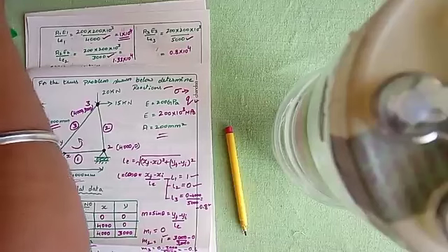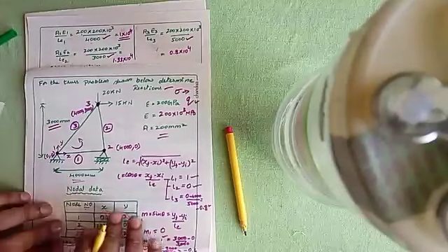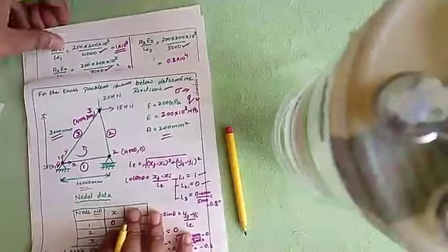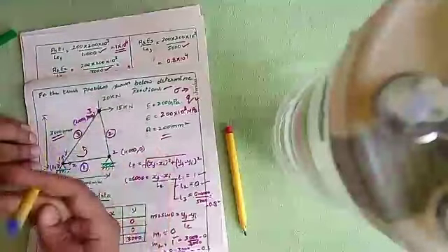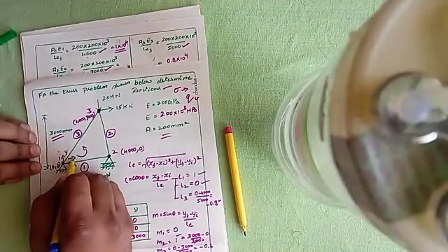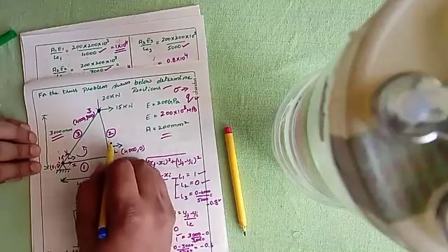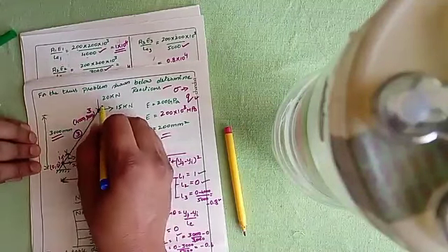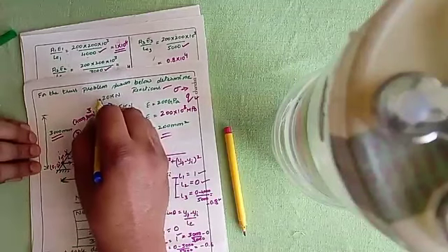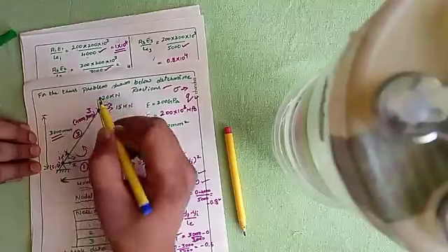Okay, this is very much important. Now at node number 1, how many degrees of freedom do we have? Since this is a truss, you have a coordinate system x and y. So you're going to get two displacements, one along the x direction and one along the y direction. Meanwhile, here also you're going to get one displacement along the x direction and one displacement along the y direction.